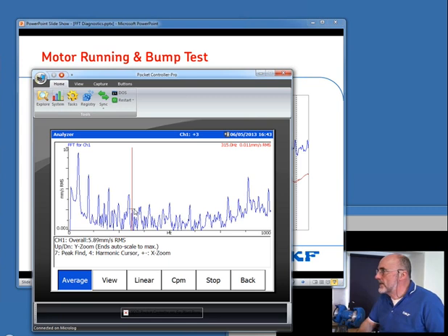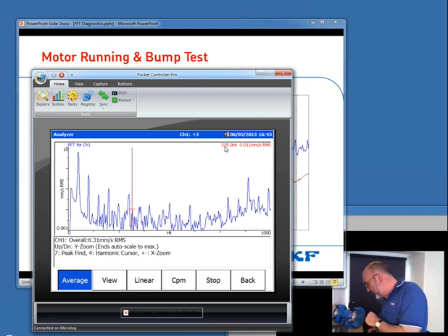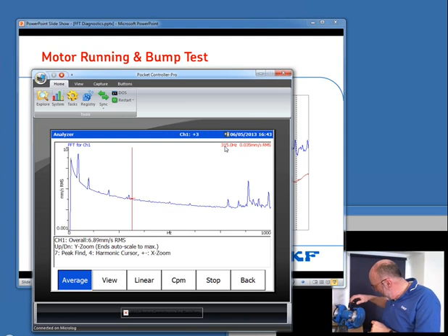It's coming out at 315 Hertz, which is not an integer multiple of 50, which is evidence that that is structural. If it was a gearbox and there was a funny gearbox ratio, it might be some kind of funny gearbox ratio. But what the classic test you can do is to